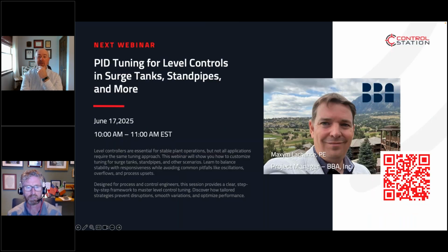I've seen that there are some smart positioner vendors that claim their positioners have an algorithm that will account for some of the stiction and give the valve a little extra boost each time you try to get the valve to move, to overcome that stiction in the short term. So that's something you can look at if it's a feature of the positioner you happen to have already. But I much prefer to fix the root cause than to keep slapping band-aids on top, but that is another possible solution.